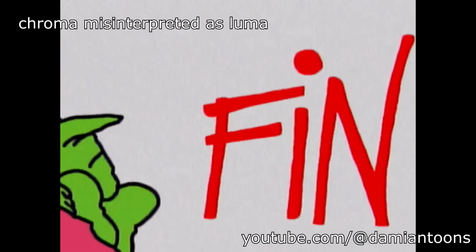This can cause dot crawl, or cross-luminance, where a sudden change in color, like the edges of these red letters, gets misinterpreted as a shimmering luma change. This actually looks like an accident, not intentional. But this is not the kind of glitch that the CoCo exploits for its high-resolution black and white graphics screen. Instead, it relies on the reverse problem. What happens when luma gets misinterpreted as chroma?